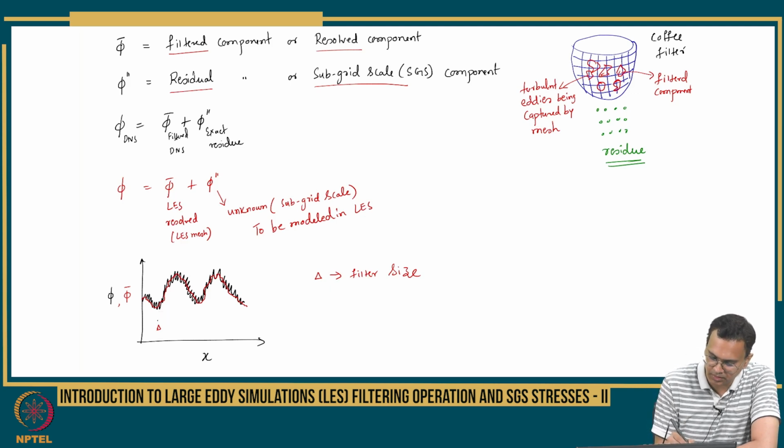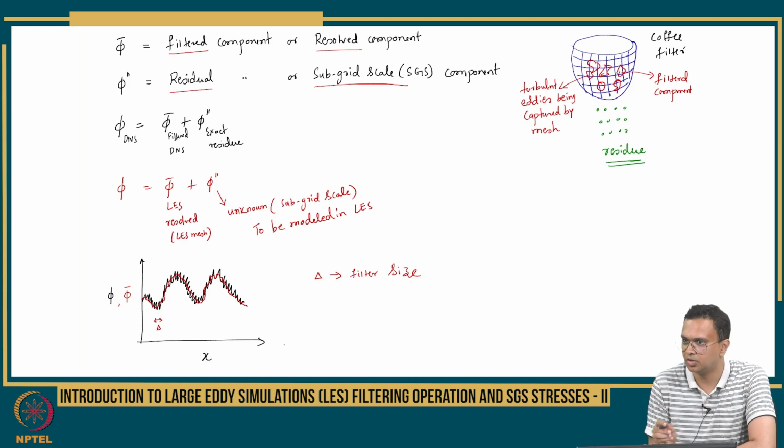If you change the filter size, the signal will look different. Depending on the cutoff frequency in the low pass filtering, your signal will look more and more smooth. The more frequencies you cut off, the smoother it looks. It may even become like an actual sine wave, right? But that means you decide here.